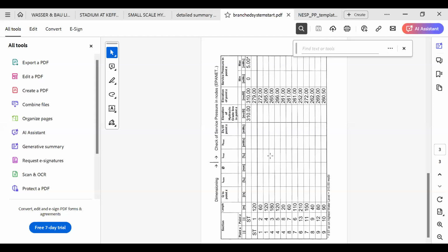Okay, so with these 2 parameters in place, you now need to find out the other 2 parameters. Those are the liters per second, which is the water demand, and the slope. Column 4 is talking about the slope. Are we together? Yes. Good. Then column 5 is now the diameter.